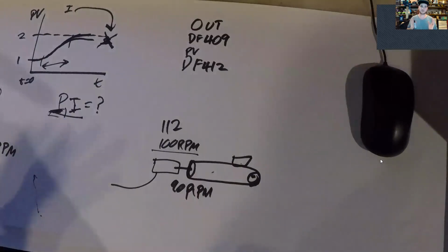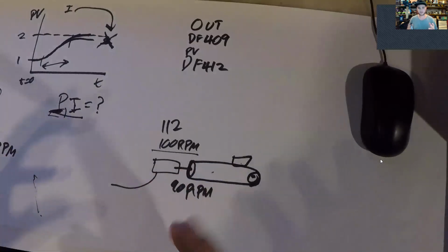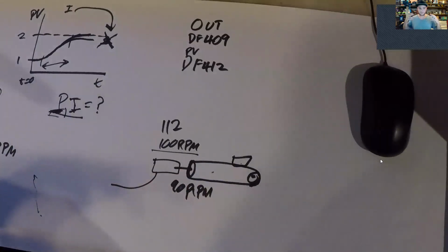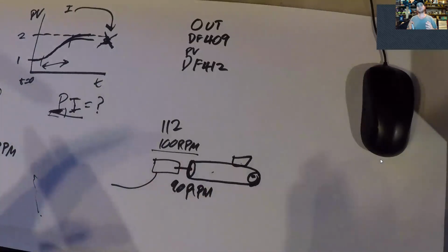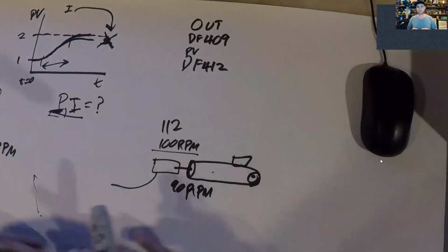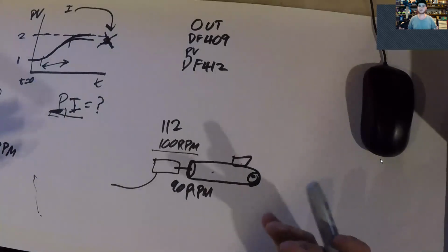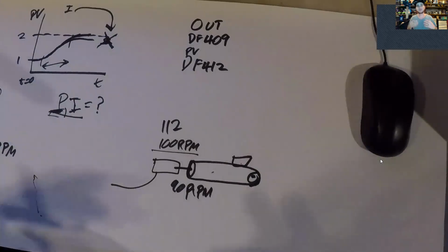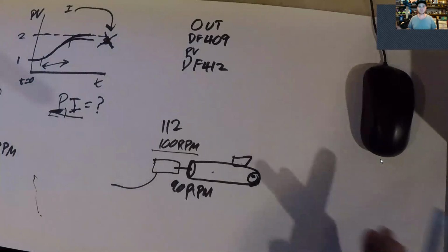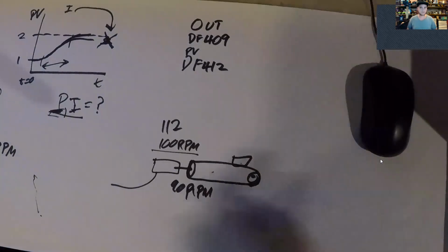So that's another important point, to limit your output into a physically logical bounded range. Because if you try to put an output with your controller that isn't physically achievable with the hardware you have, then there's no way you can ever get your controller tuned correctly, because you're always going to be trying to do stuff you can't do, right?